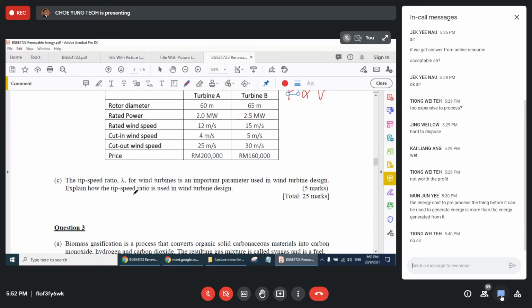So when we do the turbine design, the tip speed ratio means the ratio of the speed of the tip of the blade to the wind speed. We call it the tip speed ratio. This is used by the wind turbine designer to properly match the optimum blade to the generator. You want the blade to rotate at the same speed that the generator needs. So you have to adjust properly so that they can have the proper mesh. First, you can save or reduce the size of the gear. So this is actually very important, to select the blade to mesh with the generator.